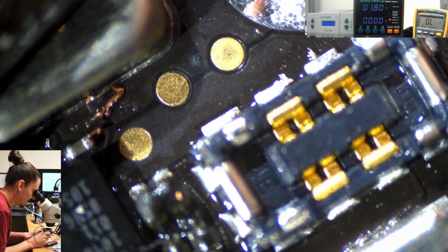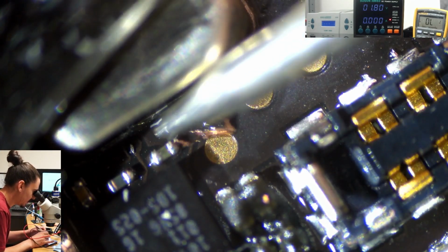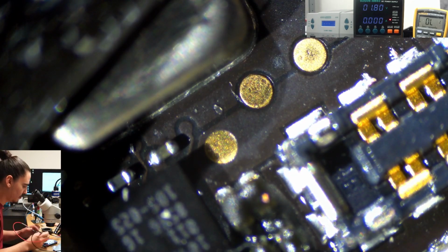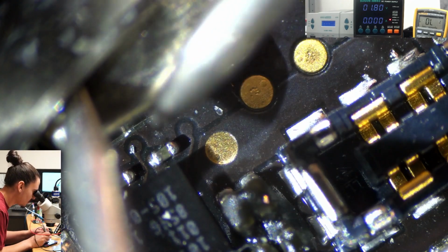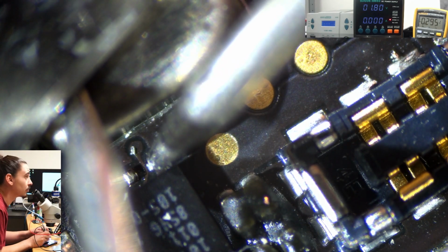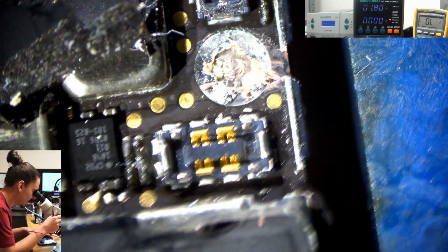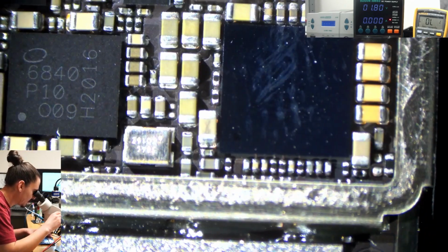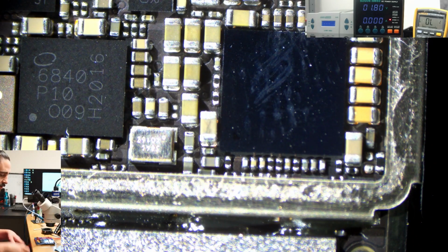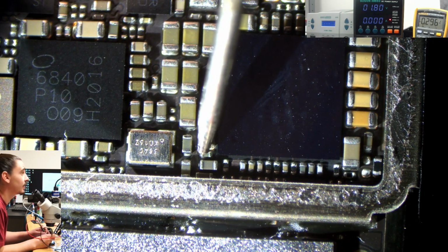It's always good to just check, make sure I'm still short. I'll just do that quickly now. It looks like it's already clear, so I don't need to dig any further than this. That's great. Hopefully that's all I need to do. I may have more issues down there, but I'm not sure. So if I go back to this original capacitor I was measuring the short at, I should no longer see a short at that line. And I do not.